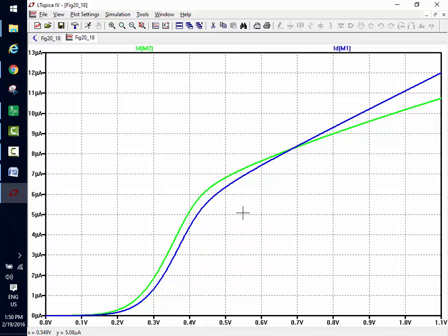The reason for that is the nanometer processes have really poor output resistances. So if you look at the curves from chapter 6 or chapter 9 in the book, and you look at the IV curves, they look like this. You know, they're really slopey, and that's modern process. That's the way they do it. Everything gets smaller and smaller. They still have to make things work.